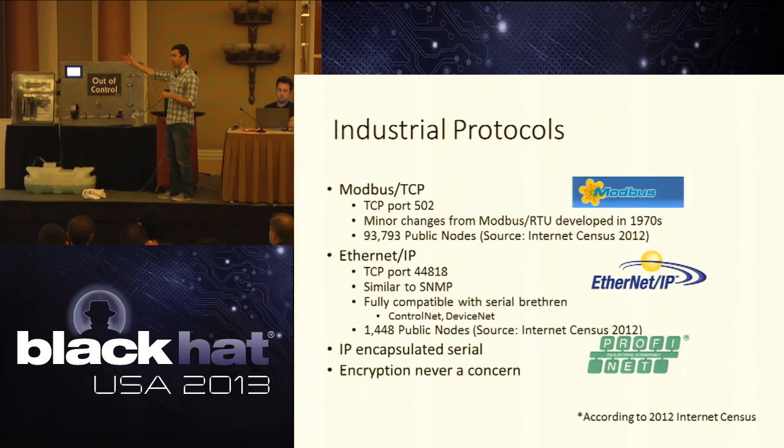So we have a couple other protocols that are open and are used pretty widely. Ethernet IP is one, Profinet is one. But, like I said, there's an obvious reason why we chose TCP, and it's up there. Because there are 93,000 nodes on the internet, from the internet census of 2012, that are listening on TCP port 502. It may not necessarily be an RTU or a PLC. It might be one of these guys, but Modbus is used to control processes out in the field.